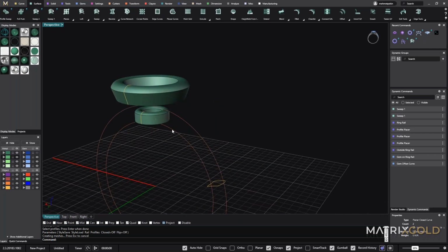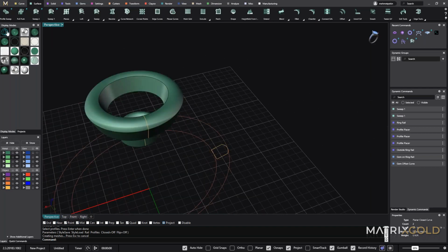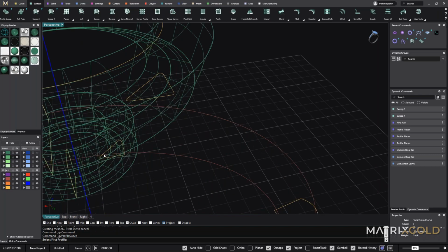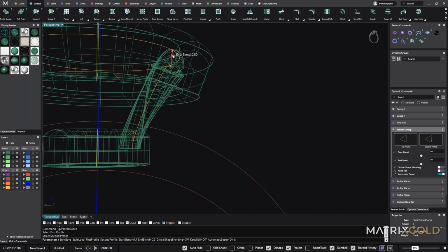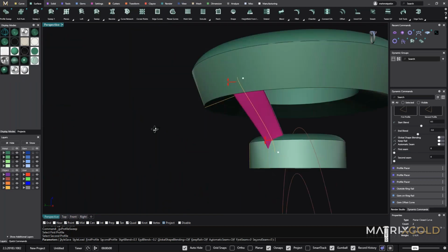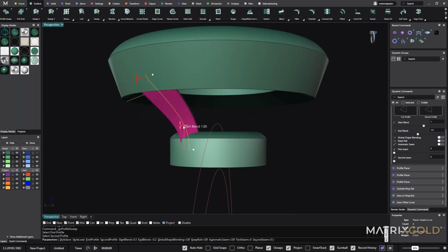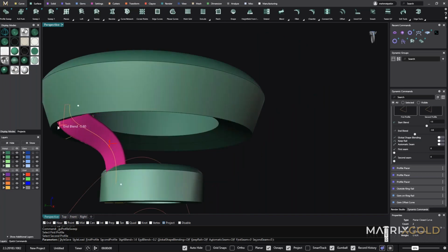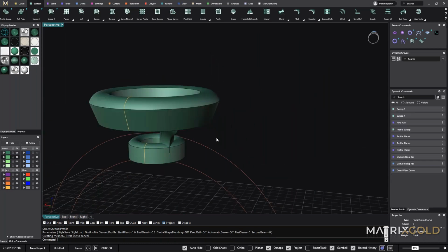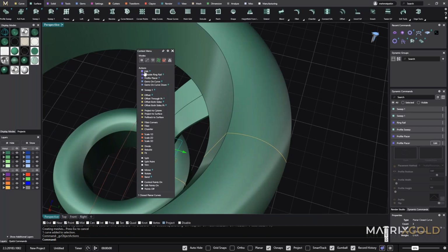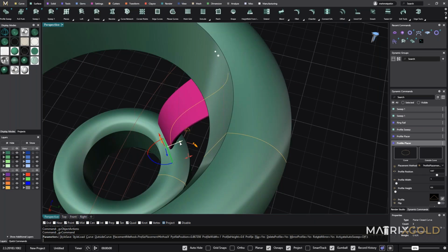Now I'm going to use this with that one with profile sweep. I'm just selecting this one and this one. Now it's the wrong side when I move like this, and you can deselect the automatic seam here, and you can take a look at that one. And you can also make something like this, maybe something like this, and maybe like this. And you can also do the same thing for here, like this. Now that's okay. And you can also change the size of the profile from here. Maybe you can select the edit button and you can move it like this.